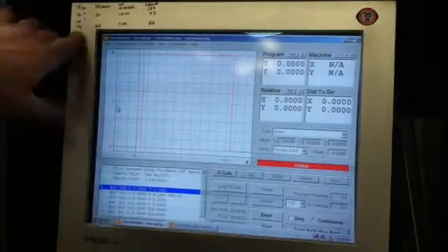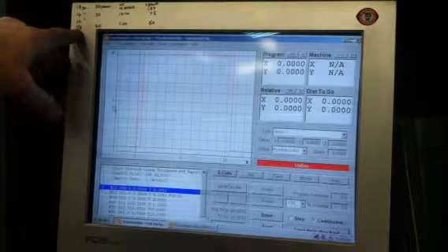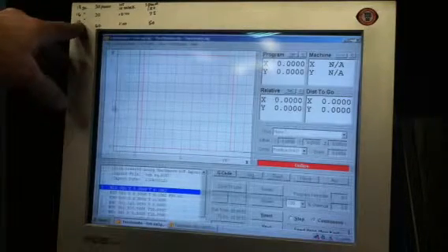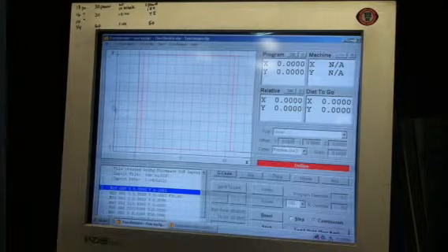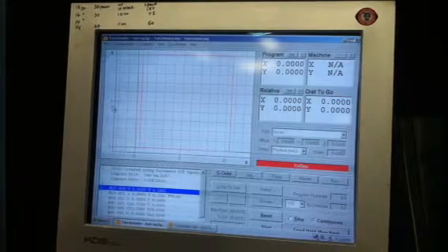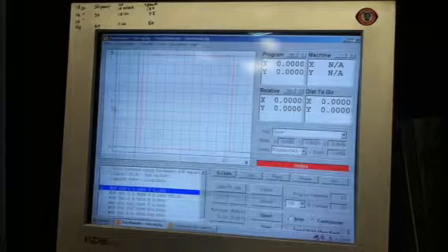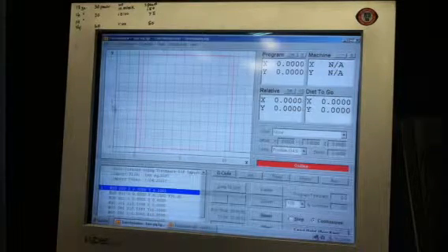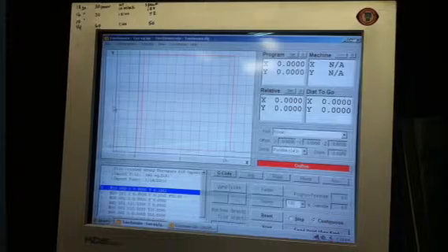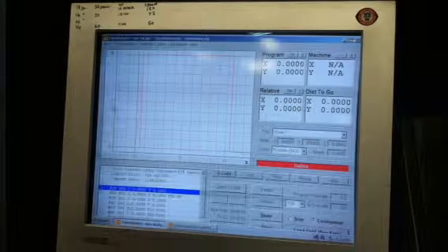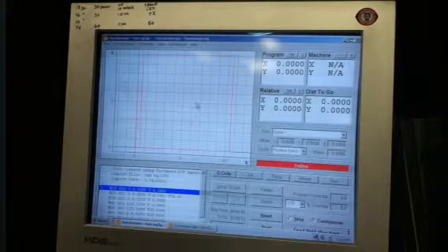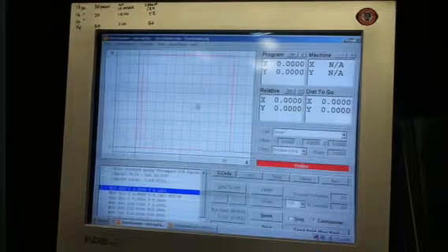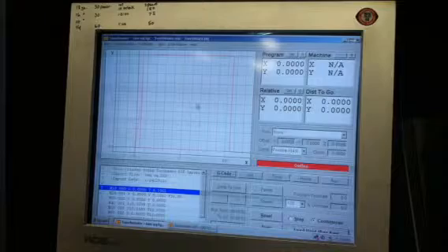So your cheat sheet's right up here for a few things on 1/4 inch plate, 10 gauge, 16 gauge, 18 gauge. I know you guys are cutting even heavier stuff. When I did the demo on the 3/4 inch plate and I cut that circle, I was running it at a speed of 15. But you'll just have to play with it to find what the optimum speeds are for whatever material you're using. If you have further questions, you can always give me a call, and hopefully I can help you out.